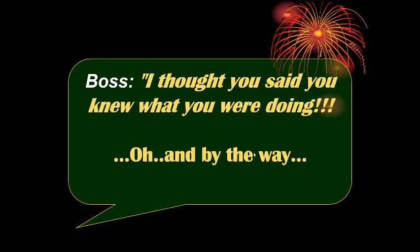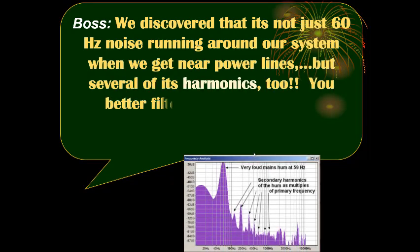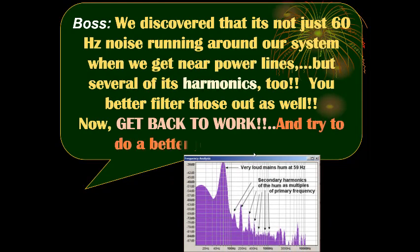Oh, and by the way, we did just discover that it's not just 60 hertz noise running around our system, but when we finally put some oscilloscopes and spectrum analyzers on it, we saw that it's not just 60 hertz, but all of its harmonics. So you better filter those out as well. So now get back to work and try to do a better job this time.